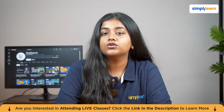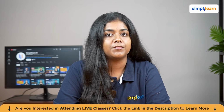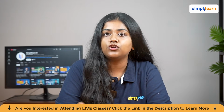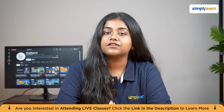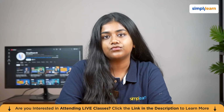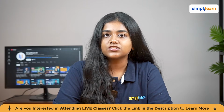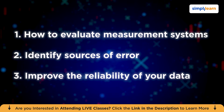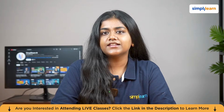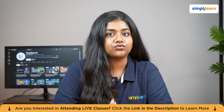Then we'll move into one of the most important areas of MSA, repeatability and reproducibility, commonly known as Gage R&R. Here you will learn how much variation comes from the measuring equipment and how much comes from the different operators using that equipment. We'll also explore the average and range method, the ANOVA method, and finally attribute gauge analysis for pass or fail inspection systems using cross-tabulation and Kappa statistics. So by the end of this course, you will understand how to evaluate measurement systems, identify sources of error, and improve the reliability of your data. So let's begin this learning journey and understand how MSA helps organizations make better, smart, and more confident quality decisions.